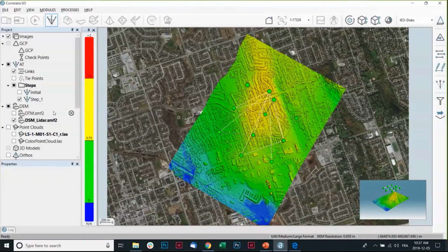I think the key to a good true ortho is having a really good surface model and a good fit between where your image was positioned when it was taken and the reference source you want to ortho rectify these images with.